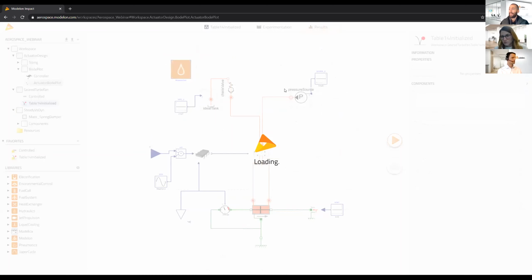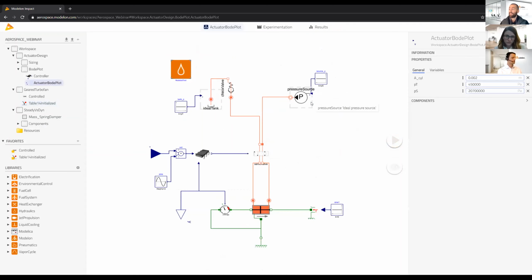So here we have a hydraulic actuator, which is a hydraulic cylinder and a control valve. It's a really simple model here. It is regulated in position. So we have a sensor that is attended to the controller. And based on the input you command and this controller, we will actually move the valve so that the power coming from the pressure source, the hydraulic power will be actually metered into the two chambers of the hydraulic cylinder. So we make sure that we can reach a given position facing a given load.